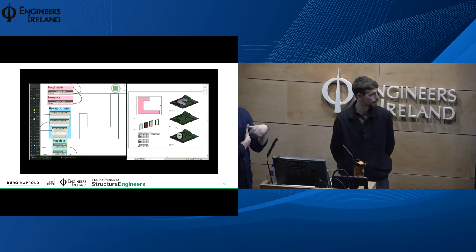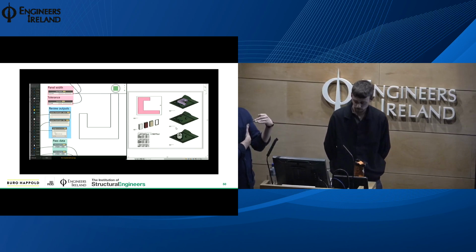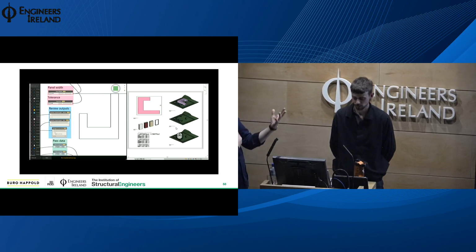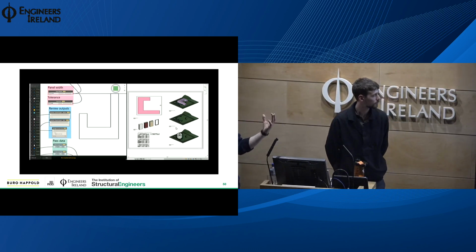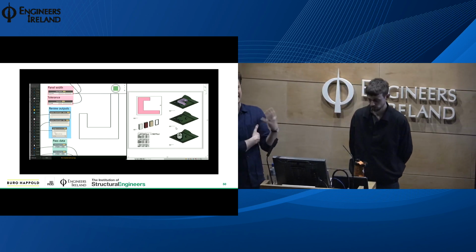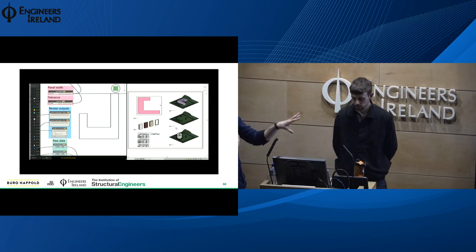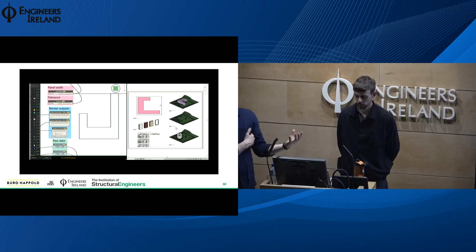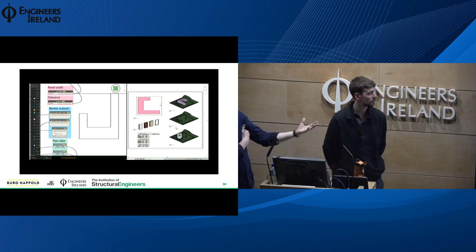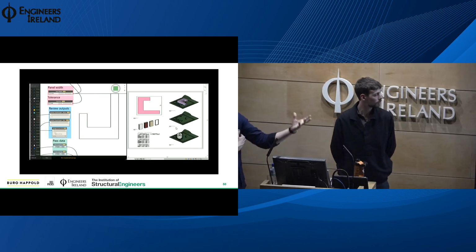Yeah, and then once in the environment that I was comfortable working in, I had received this floor plate. I was able to generate, with some scripts that we have in-house, quite a simple number of grid arrangements, so it automatically created 5 or 6 grid arrangements. Ultimately, the scripts just look to create a few more than you might come up with individually. They're looking for the facade lines, for those key internal breakpoints, and then a range of different subdivisions between those. So instead of just working to your standard 5, 6, 7.5, 9, 10 grids, we'll let this script just run away with whatever it found to be the best at the time. For this exercise, we allowed it to find what it thought to be the most efficient.